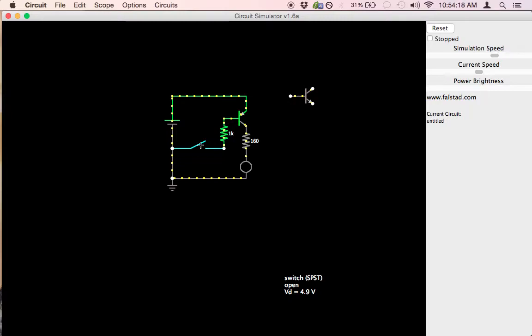We close the switch, this circuit is complete and current is able to flow from the positive terminal into the emitter, out of the base, through the current limiting resistor, and through our closed switch back to the supply. Now with the current flowing into the emitter and out of the base, the transistor is on. And it's going to allow a larger current to flow into the emitter and out of the collector. So here, once again, the collector is our output terminal, but we have a larger current flow. It's also approximately 20 milliamps, just as it was in the last circuit.